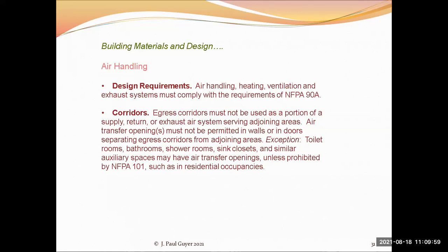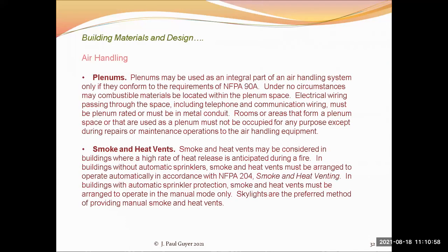And so you have fire dampers commonly used in air conditioning systems. Frequently they're activated by a fusible link that melts, and the fire damper drops down by gravity and shuts off the flow of air in the duct system at the fire rated barrier construction. Sometimes, in this day and age, these are electronically actuated automatically. But the point is that anything like a duct that passes through a fire rated barrier also has to be fire rated, and these fire dampers are fire rated. Pretty much talked about the smoke and heat vents.